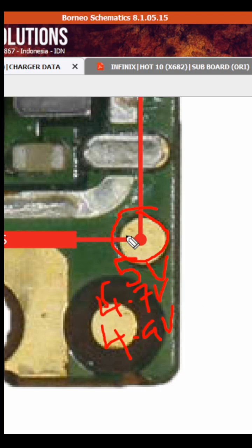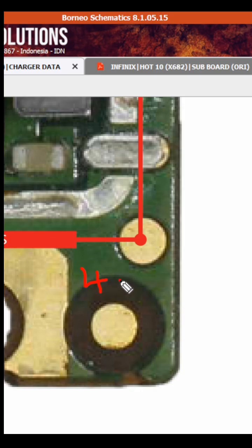This little reduction usually occurs because of the diode principle. You know that there is a diode on that subboard. If voltage passes through the diode, for that diode to switch, it will conduct some little current. That little consumption will make this voltage reduce a little bit. But yet if you approximate this, it will still give you 5 volts. So take note of that.